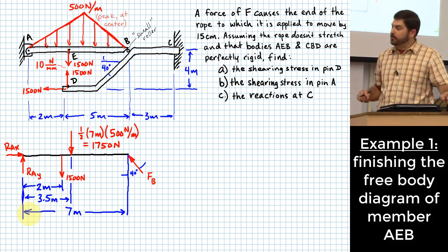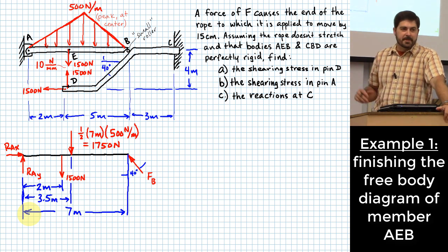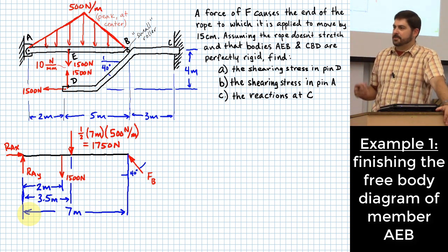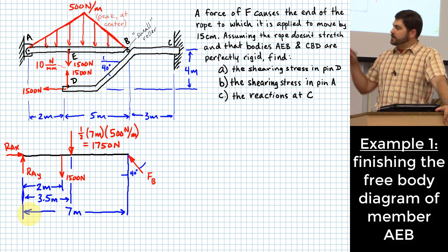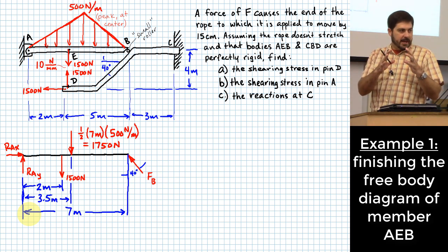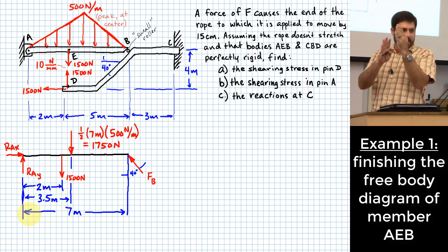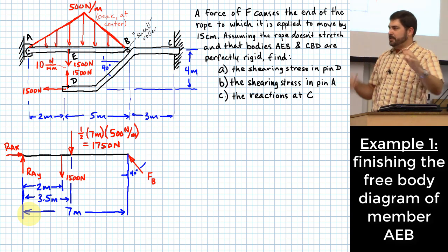Just as a comment before I move on, those of you who get used to doing mechanical drawings someday, most of you probably don't have a lot of experience with that just yet. What I've drawn here is actually generally a better way to dimension things than the way I do a lot of my figures in this class. You choose one line as your datum, as they call it, and then do all of your dimensions relative to that one line.